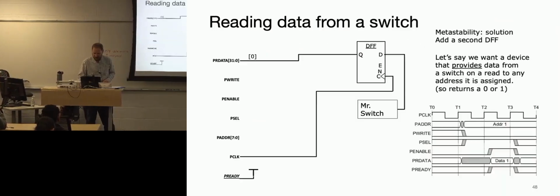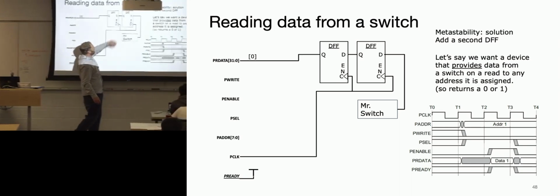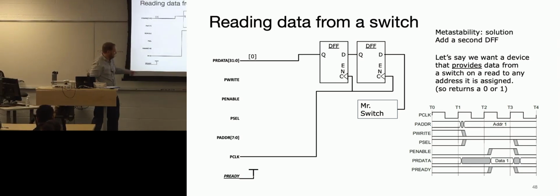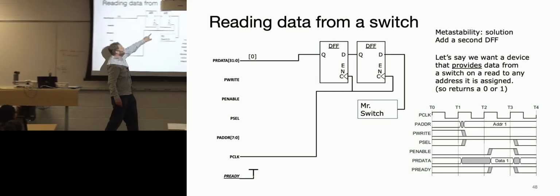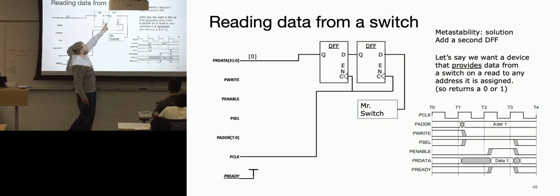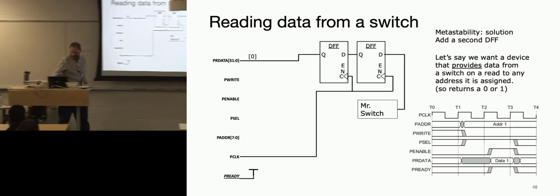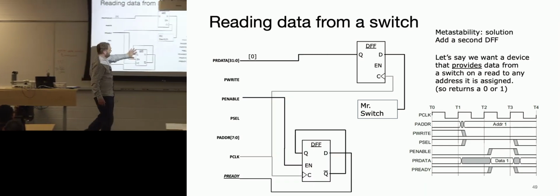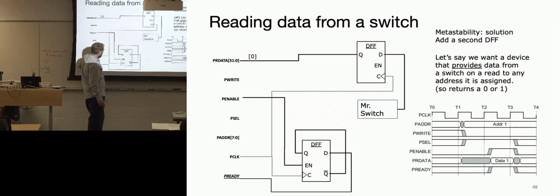There it is. Okay, so then you can modify this example to overcome this issue by putting 2 D flip-flops. Some people are pointing out the problem here: D wouldn't be immediately available. You have to wait an extra clock cycle for D to go to Q and be available on the second one, so in that case, you'd have to put in some sort of delay circuit. So I drew a crude one here and just grayed out the clock to make it a little more readable.